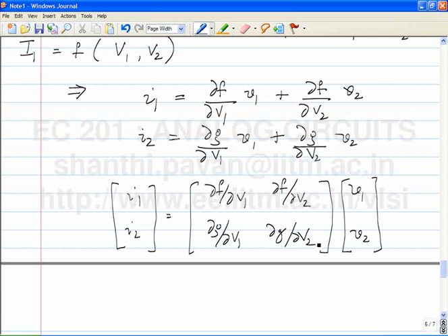Yes, which is often called, if the matrix relates I1, I2 to V1, V2, what letter do you use there? The admittance matrix, or the Y matrix. The matrix of currents is Y times the matrix of the voltages. So is this a Y matrix, or what do you qualify the Y matrix as? Incremental Y matrix. So now when you see a nonlinear two port, you find the operating points, compute the derivatives, and you have an incremental model for the incremental